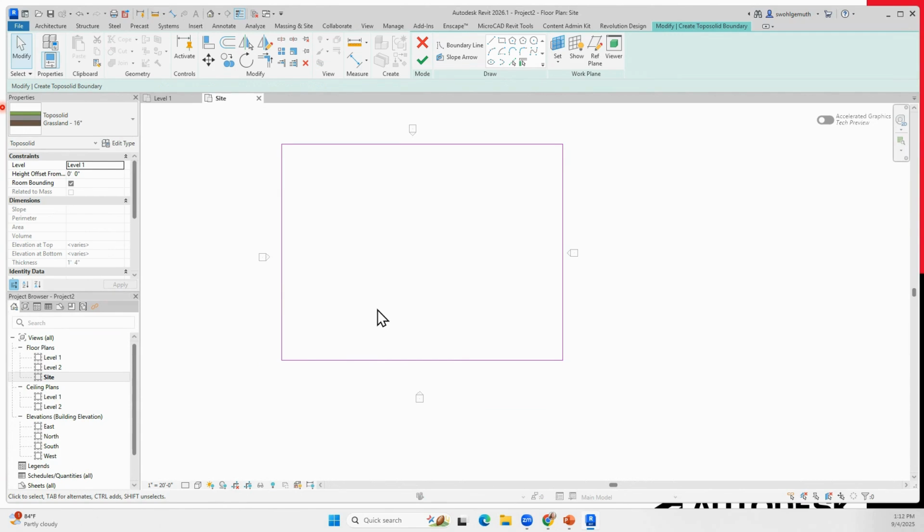when I get the CAD file from a surveyor, or when I'm using CAD files in Revit, I always clean them up. Always. Make sure that it is showing what you wanted before you bring it into Revit. Do a little bit of cleanup, do a little bit of pre-editing. Okay? So, back to my little demo here.